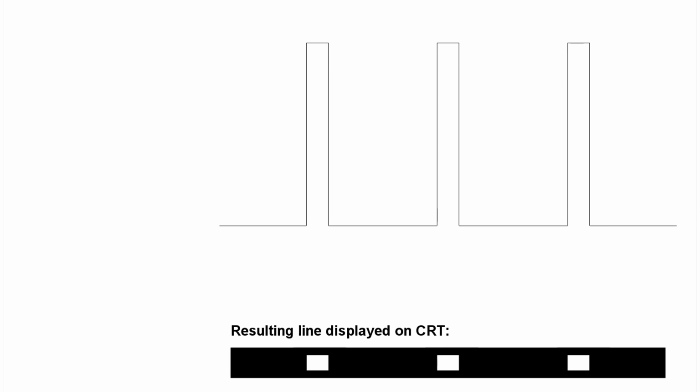A TV needs two pieces of information. First, it needs brightness information, which is sent via a luma signal, also called Y. Luma is sent as a change in voltage over time. The higher the voltage, the greater the intensity of the electron beam, and the brighter the phosphors glow at that point in time. Here's what the horizontal line traced out from this luma signal might look like.